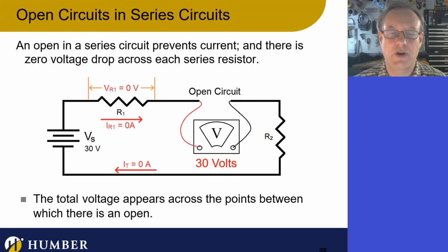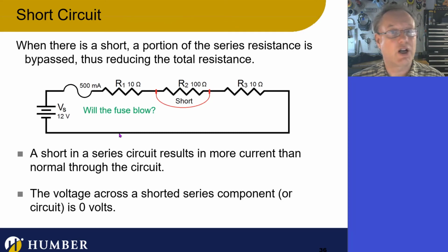Zero. So how much voltage drop exists across R1? Zero. So what's the voltage potential at the other side of R1? Vs. So that's seen on that meter. Essentially, because there's no voltage drop here, Vs is seen right there by the meter. Pretty cool. So again, there's a question on the exam like this, and the answer is whatever the Vs is. Good.